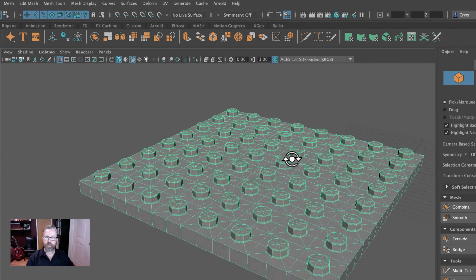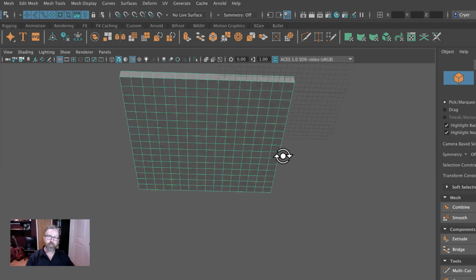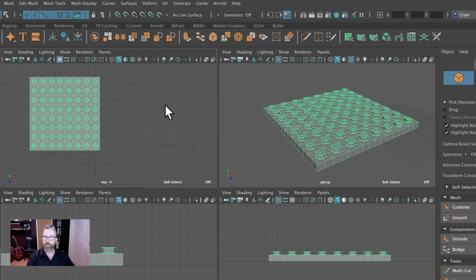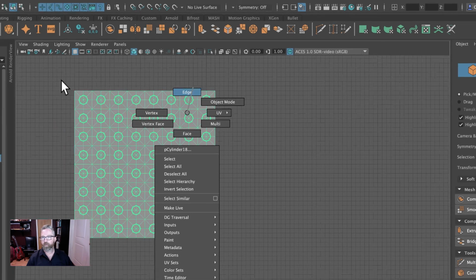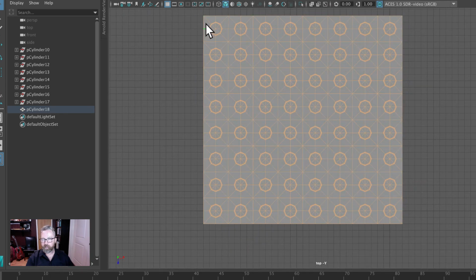And let's go ahead and bevel this. For us to use this one, it would need to be beveled. And for these ground plates, you're typically not seeing the bottom, so it would be common just to use this 8x8 with a bevel. We'll use our technique where we select all of the edges. This may be a little difficult to see. It's a great big reverse or negative selection.